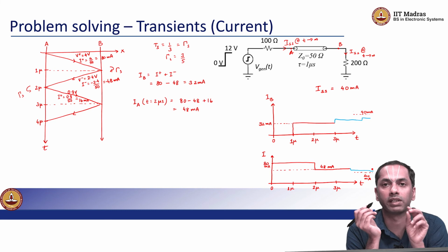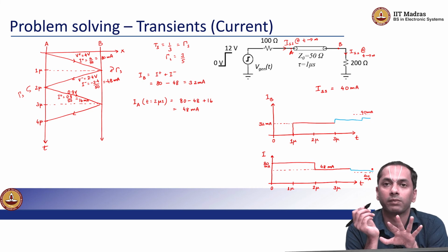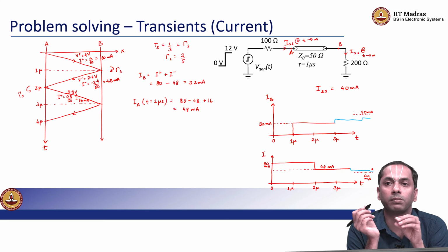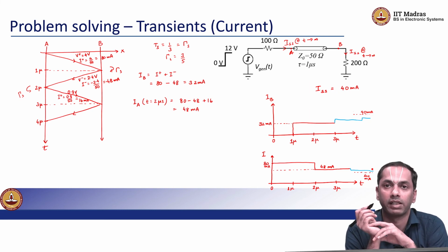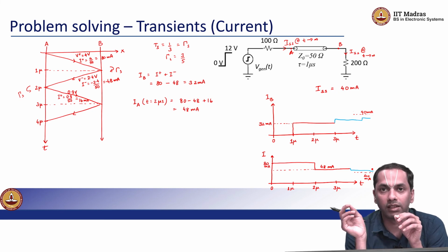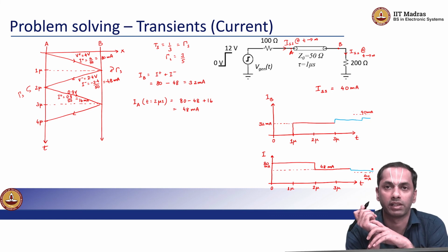Again, I would like to emphasize that this is only a transient behavior, right. According to circuit theory, at steady state, the transmission line can be replaced with a short, right. But if I am concerned with how the voltage actually reached steady state and that it took a certain time delay in order to reach the steady state value, I want to know how exactly it has taken the path to reach this steady state current or steady state voltage.